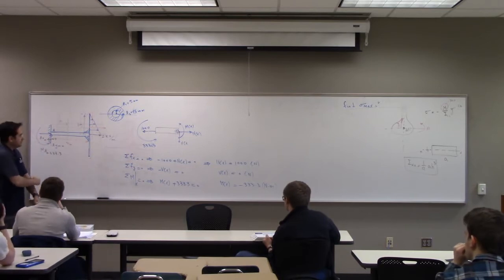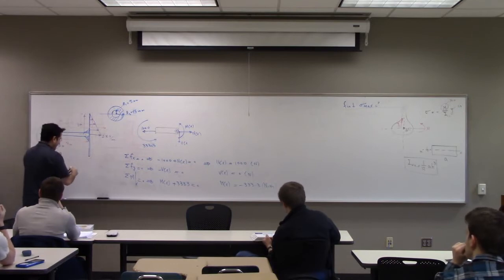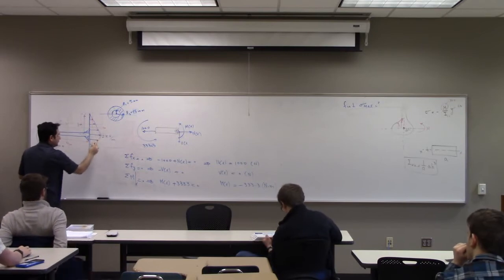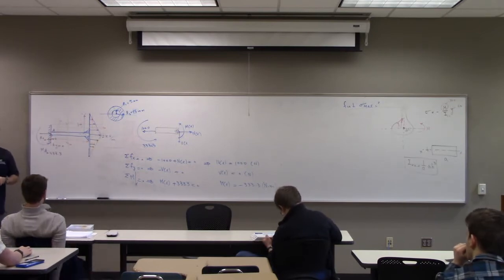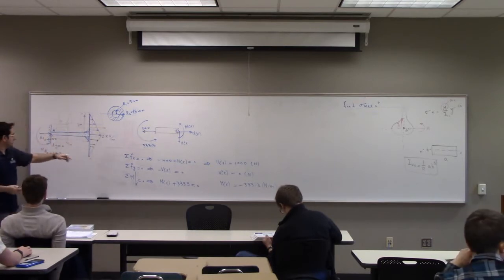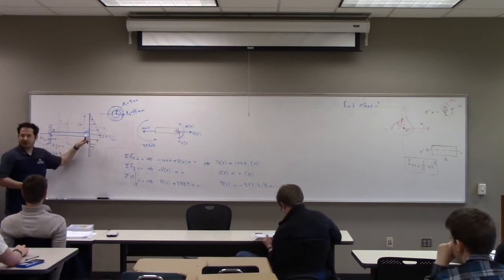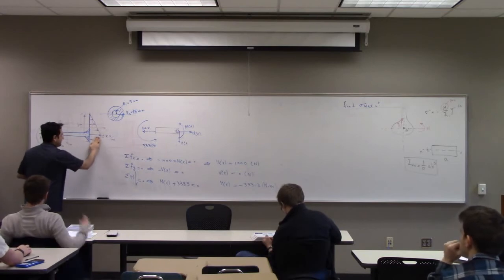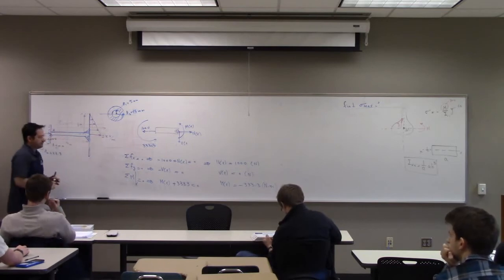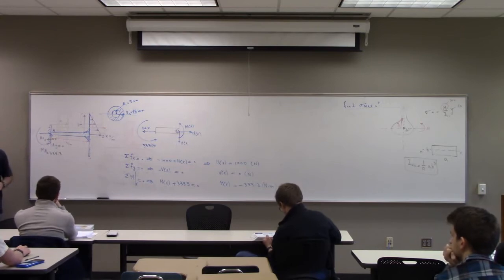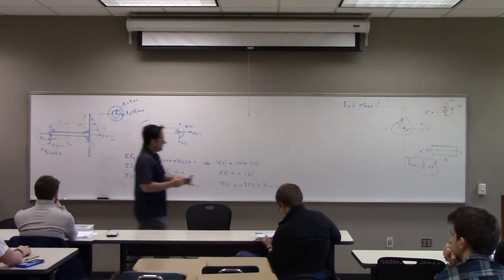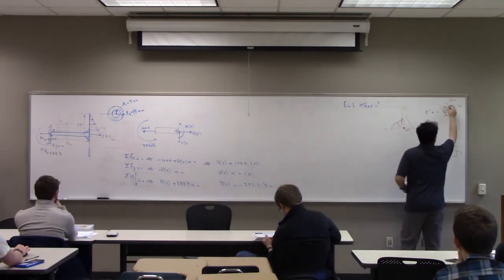Another thing, if I had something like this here, just the opposite of that, what would be the curvature, up or down? Zero. Nothing. Why? Because the moment becomes zero. If you do the same thing from scratch, you realize the effects cancel each other. The only thing you get is the axial load. But here, I don't have that, so I get some moment because it's not symmetric.